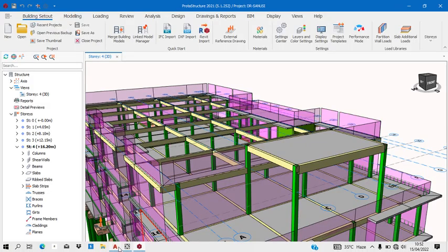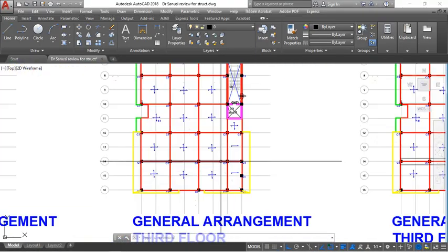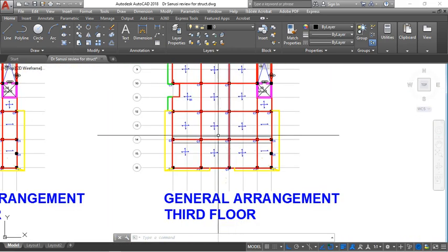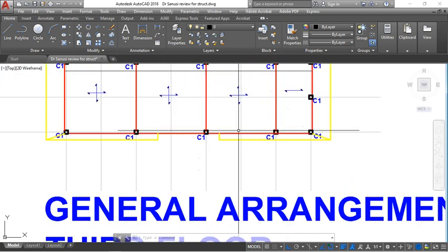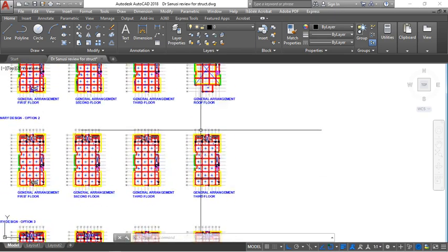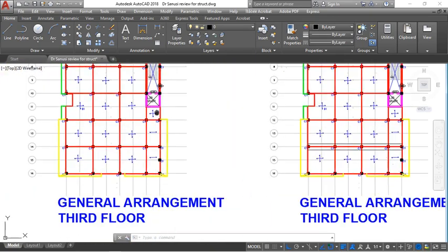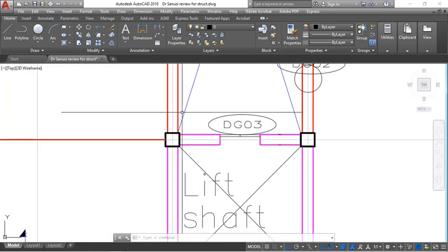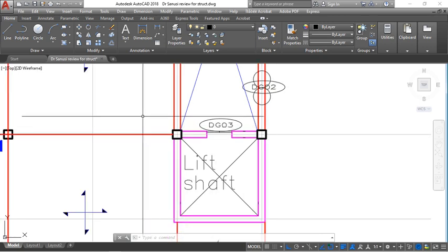So that is that. Like I said, going by this, you might need to have additional beams to support the columns that will be shifted to accommodate the final slab on that roof level. Then again, one thing I want to point out is that during analysis, when we get to that point, I will show that there's what they call axial shortening.